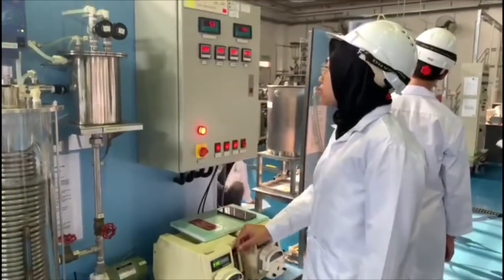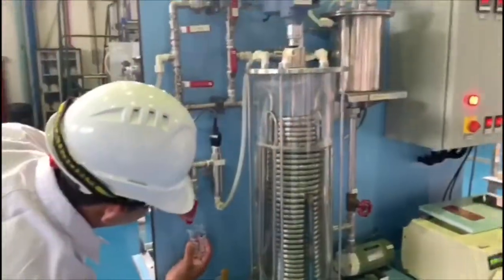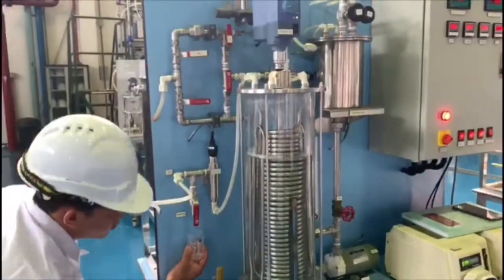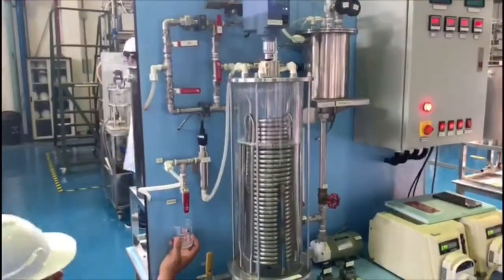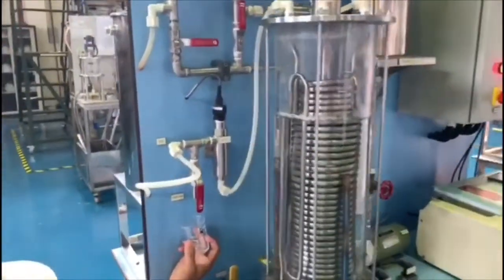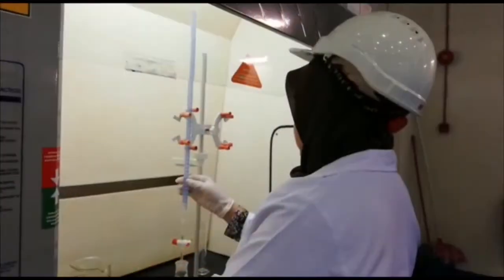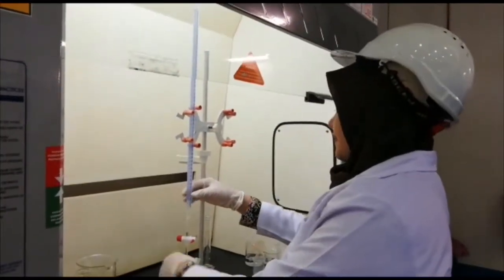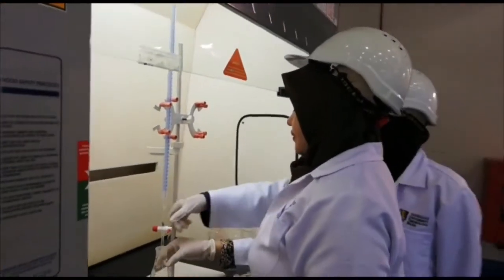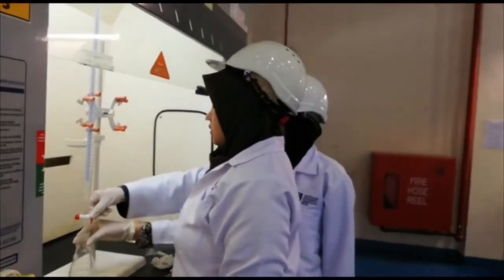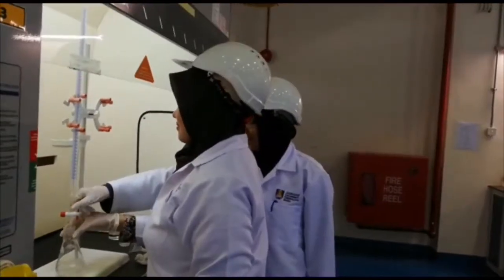Find the concentration of NaOH exiting the reactor and extent of conversion from the calibration curve. Seventh, open sampling valve V15 and collect a 50 ml sample. Carry out a back titration procedure to manually determine the concentration of NaOH in the reactor and extent of conversion.